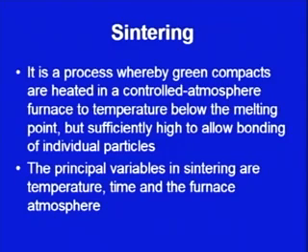So, the basic process here is that we are not going to melt the metal powders, they will be used in the solid state only. So, why is heating required? The metal powders are heated to a temperature below the melting point, but sufficiently high to allow bonding of individual particles. So, in the process of sintering, we will see this concept or the mechanism of bonding with the help of certain diagrams.